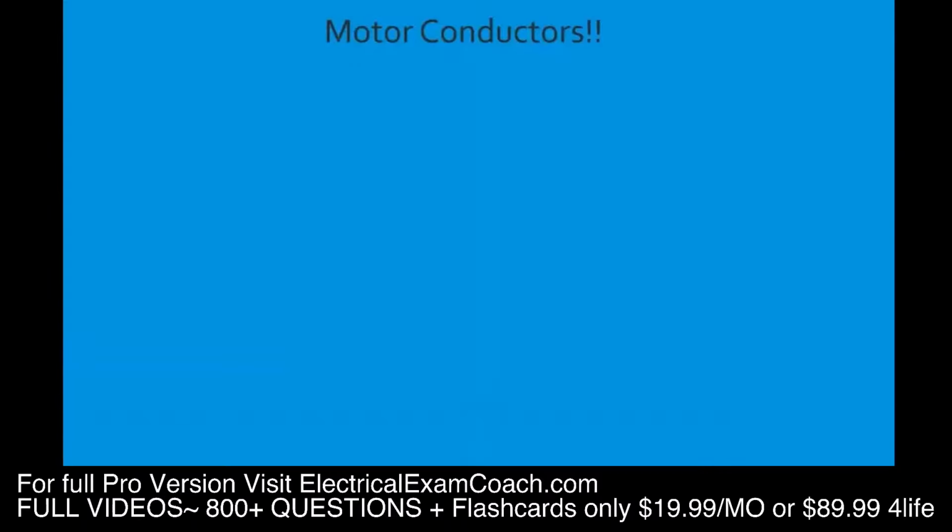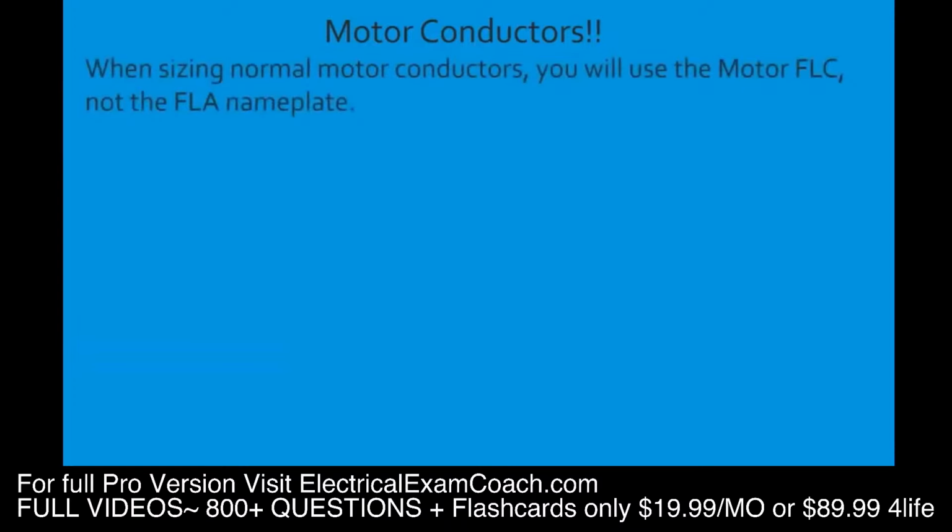Let's get to it. Now we're going to learn about sizing motor conductors. 430 is one of the largest articles in the code book, so I'm only going to show you what you're going to be testing on. When sizing normal motor conductors, you will use the motor FLC and not the FLA nameplate. FLC stands for full load current, and that's a value that we find inside the code book.